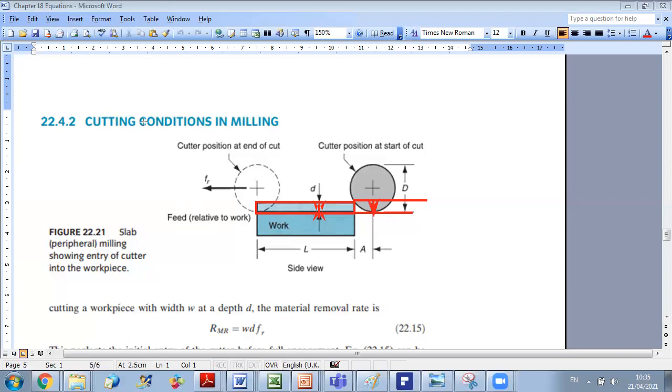Okay. Now, the parameters used in milling are the following. First, to get the removal rate, you can always derive the formulas when you understand what the removal rate is. As I am moving over this cross section, if I consider that the length of my cutter is larger than the length of my work part, in this way I can remove the complete width of the work part.